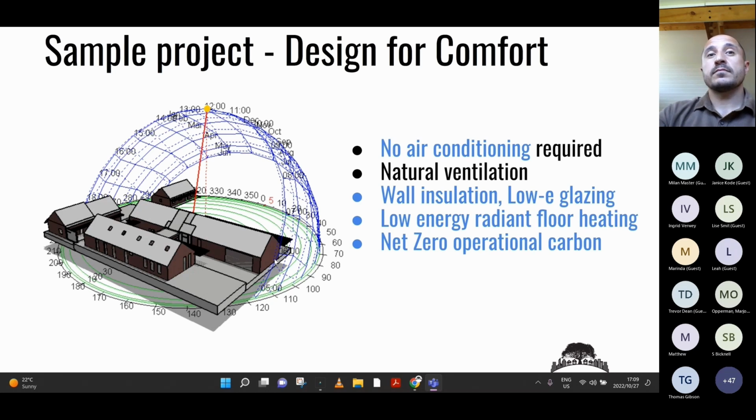But as a technology, I think in a hotel environment you'll probably find that it works well because you have both heating and cooling. One of the issues with ground source heat pumps is that you need a balanced load. So if you're going to do only heating or only cooling, then over time the effectiveness of the system reduces because you are only ever pulling heat out or putting heat in.